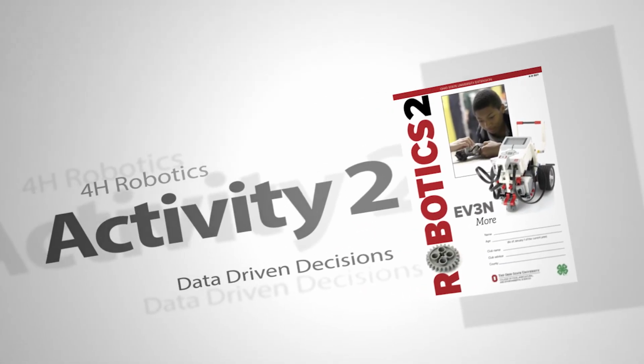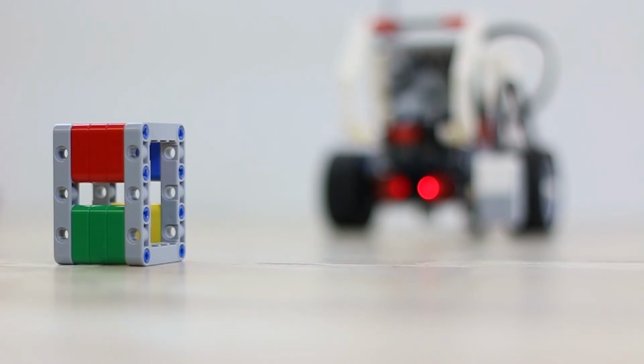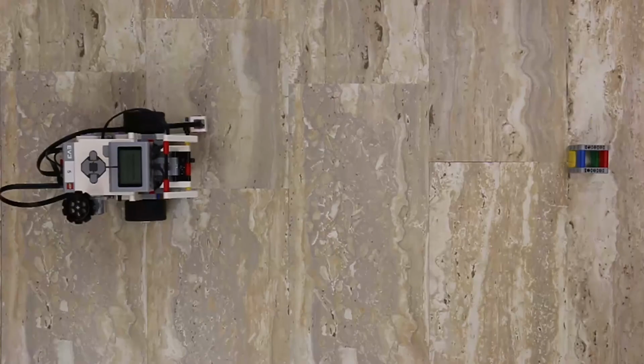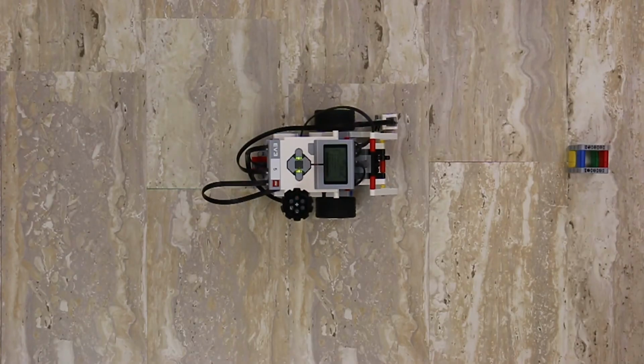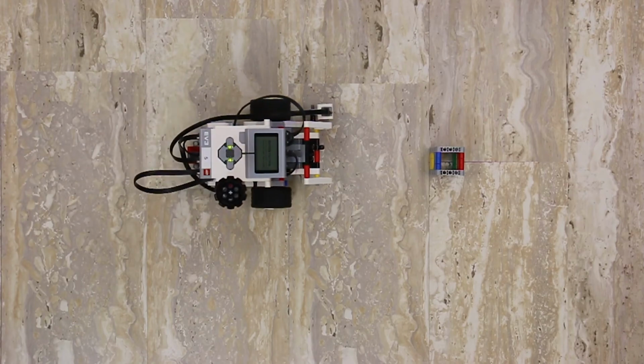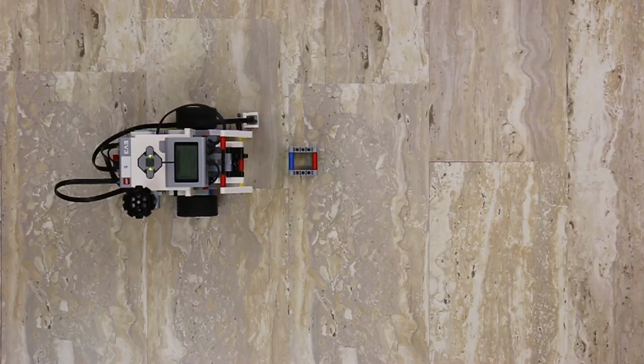Activity 2. Data-driven decisions. Sometimes a robot needs to change its behavior based on changes in the environment. In order to do this, we need to give our robot data or information from a sensor and then use that data to drive something on the robot. In this case, we're going to change the motor power based on the ultrasonic sensor reading.